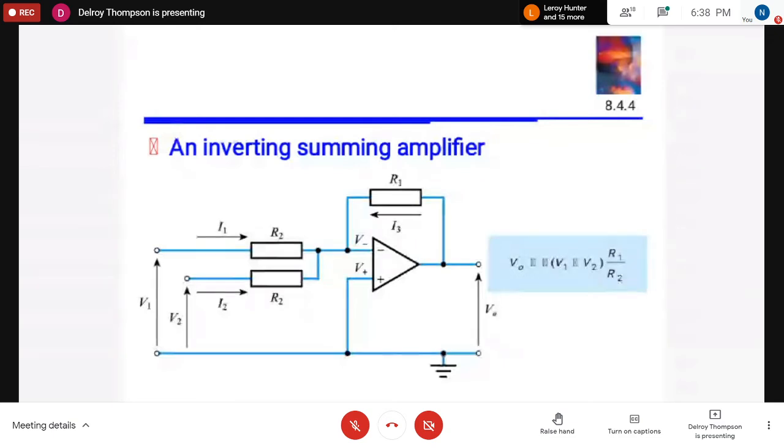So we know from what we've done before that it is going to be amplified and outputted. So we have an output current that's going to be fed back through RF. Remember we said we're changing this to RF, right? So from what we did before, IT, which is the total current, is going to be equal but opposite to I3, or if you want to call it IF, the feedback current, right? Yes, sir. Cool.